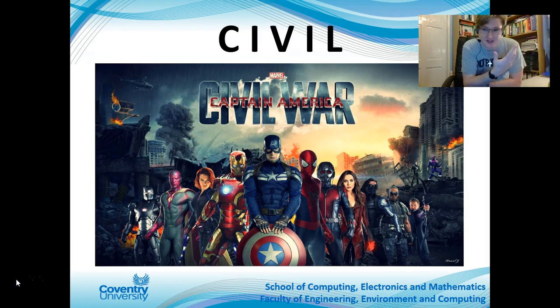So yeah, it's not quite civil war, but the expression is called CIVIL. So the C stands for capacitor, and in a capacitive circuit, the current I is leading the voltage V. For an inductive circuit, so that's your L, the voltage leads the current.